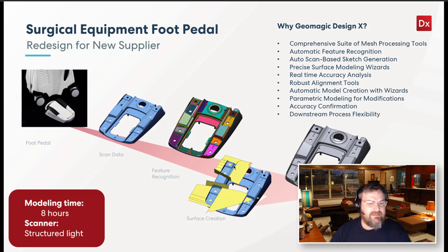In this instance, the medical world has this piece of surgical equipment, this foot pedal, and we went ahead and scanned that. As you can see, it has a lot of features to it. We captured that information with a white light structured light scanner, and then brought it into Design X for modeling. So with that, I'll go ahead and switch over to Design X.